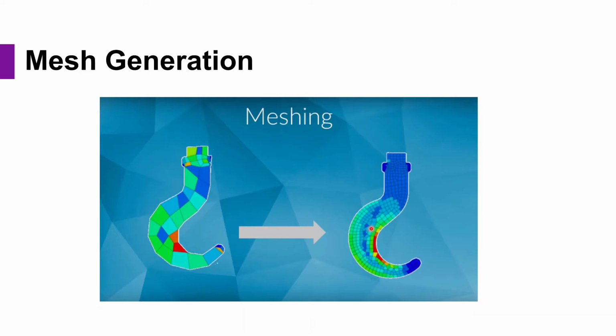So why wouldn't we go by default to 1,000,000 from the beginning, or 10,000,000 from the beginning? What would limit me from going there? The answer is computer power. If I go to a much more refined mesh, I need much more computer power to analyze it. Sometimes, for instance, to analyze the wing of an airplane, it might take around a month to apply a fully refined, really good refined mesh using high performance computers.